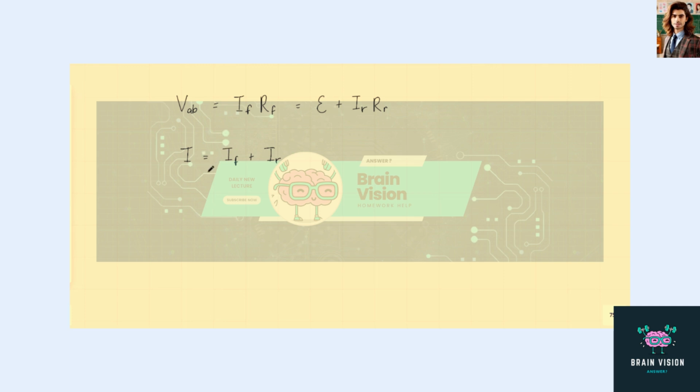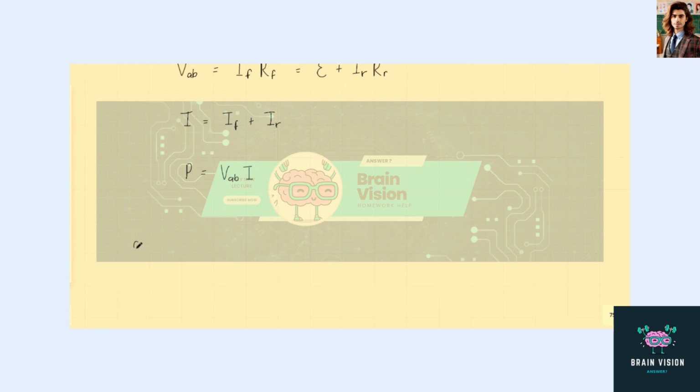The power input to the motor, P, is equal to VAB times the current drawn I. And we also know that the power output of the motor is the power input minus whatever power losses occur due to the resistances and the friction. So let's find first the field current, IF.